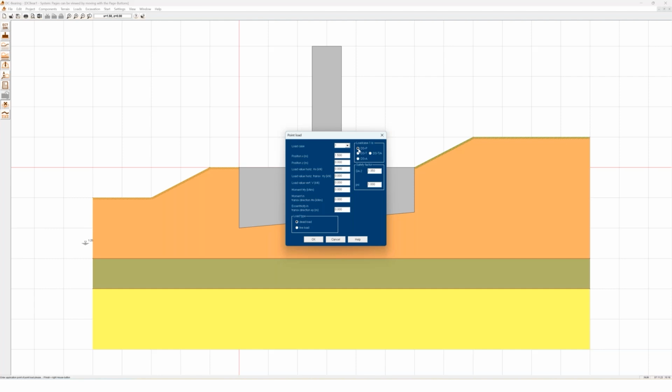So it has no load case combination. So if you want to have loads combined with each other, it must always be in one load case. So the verification is separated for each load case and excavation stage.